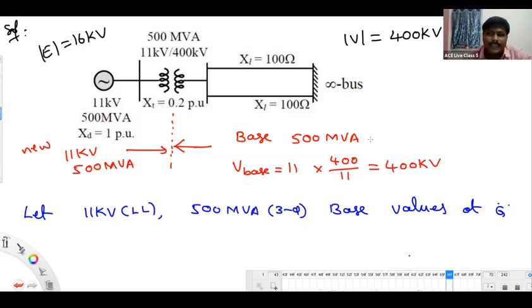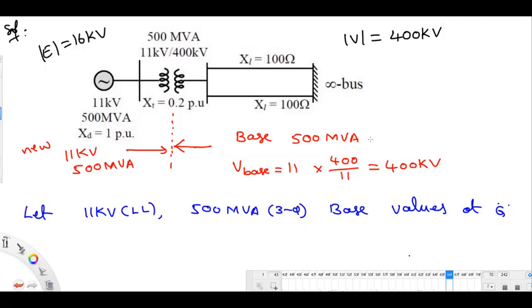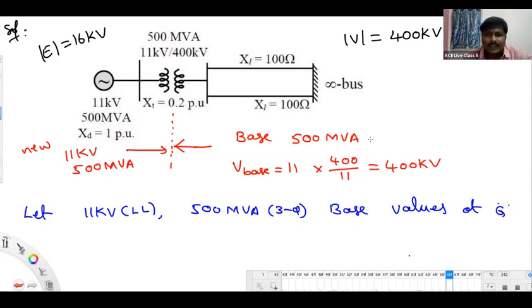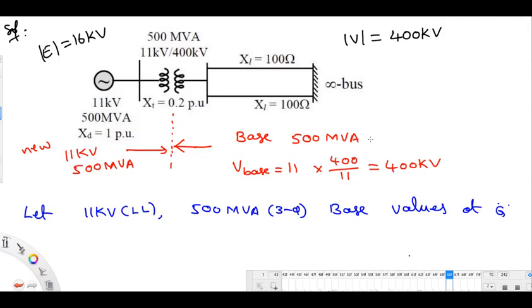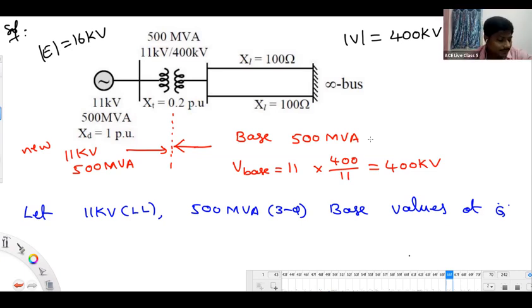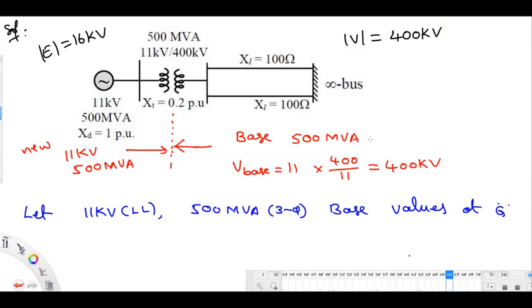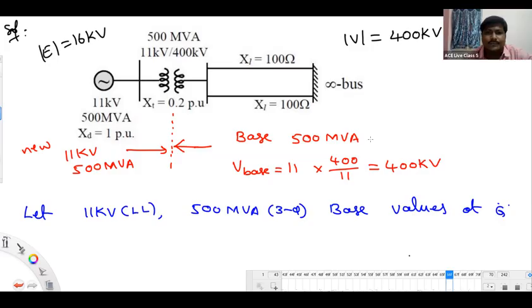On the 400 kV bus bar, 3 reactors you observe: phase A, phase B, phase C. Yes, sir. Might be connected in star or delta. Might be star, I think so. Star solidly grounded. Okay, sir. Maybe 40 MVA reactor, 40 or 50 MVA reactor. Okay, sir. Got it, sir. Thank you, sir.